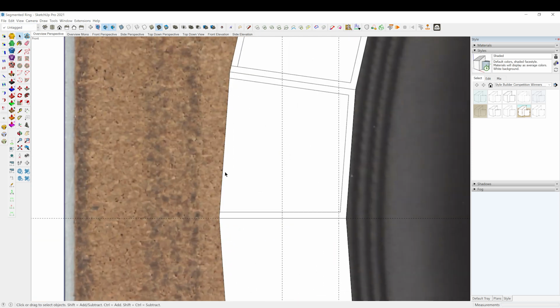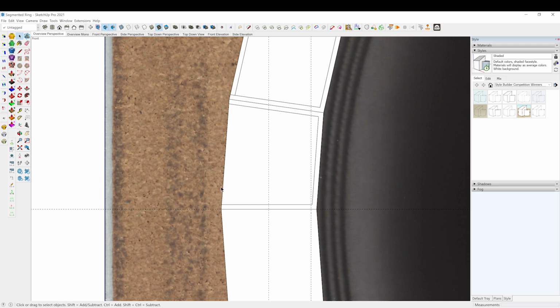All right, so now to measure the angle, this line here is what's going to reference off my miter gauge. So I'm just going to grab my protractor tool and just measure what that angle is, and that's 86 degrees. So when I set my protractor, I'm going to do 86 minus 90, so I'm going to set my miter gauge up at 4 degrees. All right, so this one's 4 degrees, so I'm just going to mark that in.